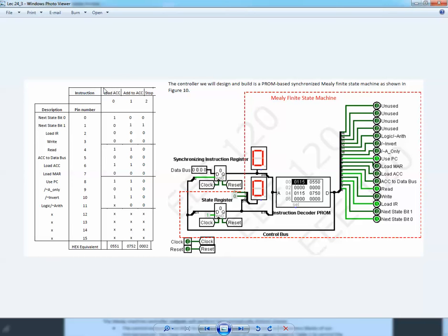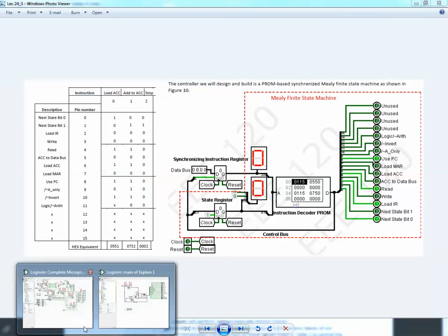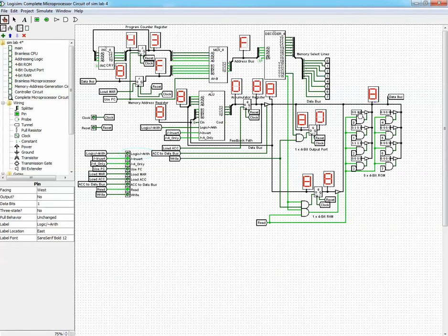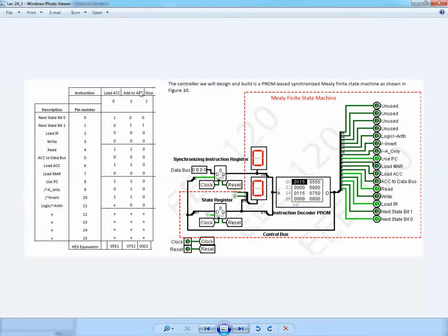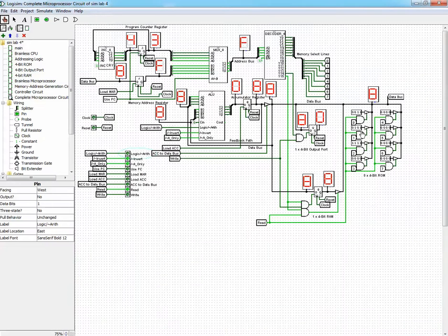And this is why you expect, when you want to load ACC, you want to load it with number 3. So you expect that number 3 will be stored in this value. Okay, this is why I've stored number 3 in the first clock cycle. Okay, again, what about number 5? Number 5 will be stored in the second clock cycle. Okay, this is why I've stored 0101 in 5 here, while the remaining we do not really care about them. Okay, so everything will be 0.